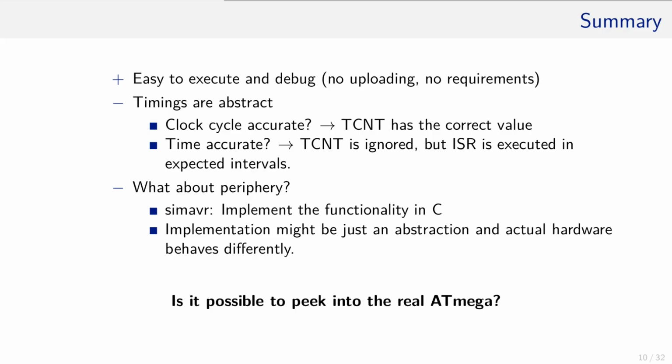While it is possible to implement behavior of peripheries in C and easily integrate them in simavr, the software developer must decide if it is worth the time and effort. There is always the danger that the model of the periphery is too abstract or too ideal and hence its behavior too distant from the actual hardware device. Maybe the ATmega user program is debugged to run with the simulated periphery, but it will not work with the actual one. Therefore, it would be a good idea to have the option to peek and step through the actual user program that runs on a real ATmega.